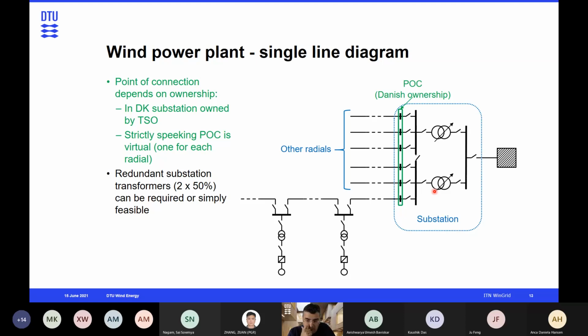So typically there are two offshore transformers with a 50-50 kind of rating, or even different, a bit overrated. So in case one transformer is out, it can still transfer an amount of power through the other transformer, and all those are then connected to the shore.